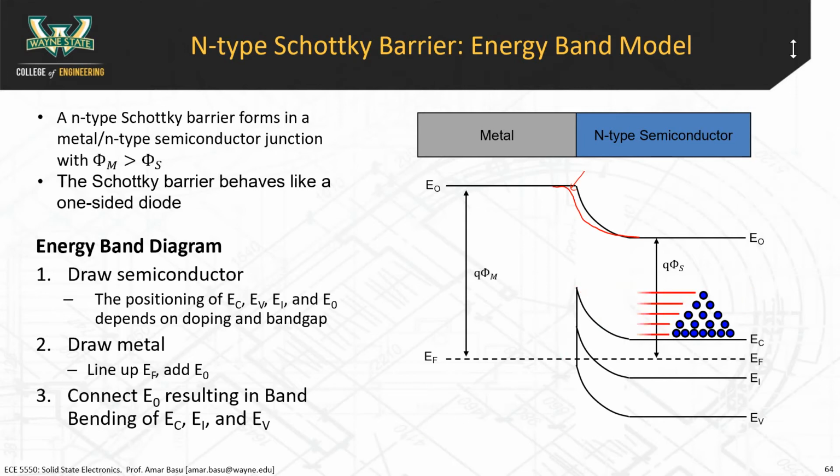So where were we here? Yeah, so the equilibrium that's quickly established at the right side of the band diagram came down. Okay, and now the Fermi levels are lined up, but because E0 has to be connected, you can't have E0 here and then E0 here and just have a discontinuous thing. There has to be a continuous region in the middle. So that's where this barrier forms. And once equilibrium is established, that barrier height prevents additional electrons from dumping over into the metal.